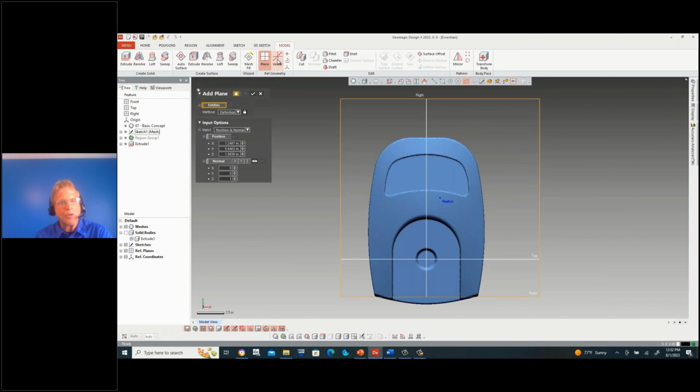Let's also go through and add some planes to the bottoms of those pockets. And we're going to use a rectangular selection tool now. And we're going to select the triangles on the bottom floor of that plane. And we'll best fit that plane through those triangles. So plane 1 is best fit through the enclosed pocket. And now the open pocket, we're going to go ahead and select triangles on that floor, but then we'll remove the triangles around the hole. And we'll select that as plane 2.